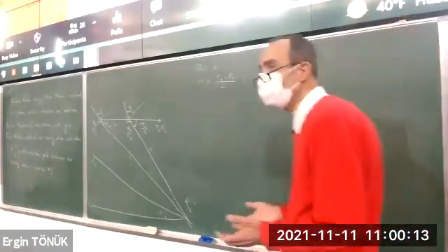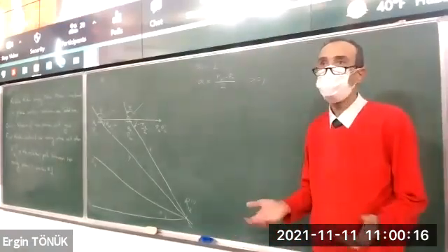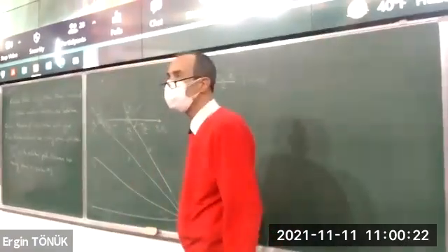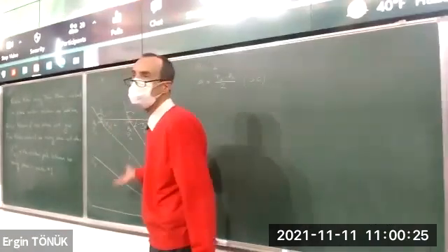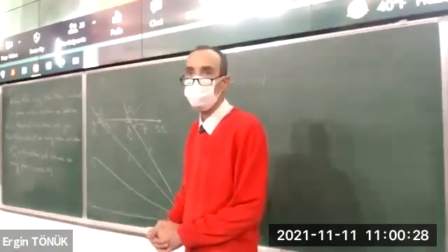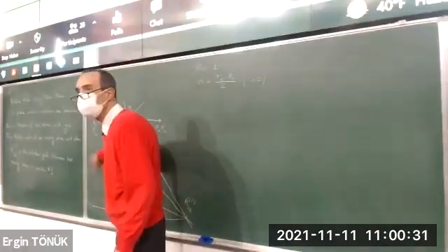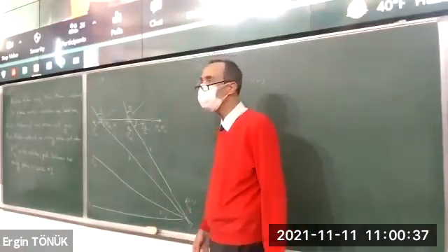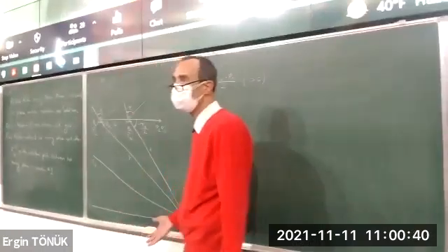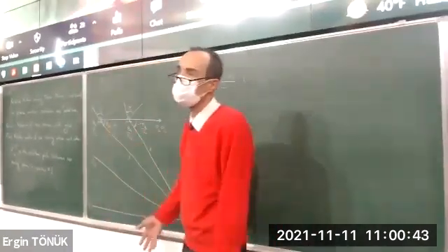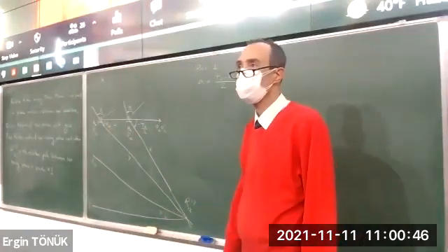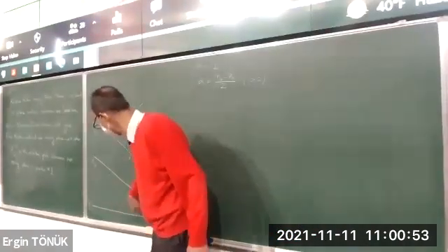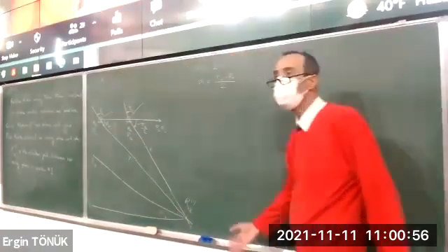That's something very good. Why? Design is an iterative process. You may just draw these lines, select A1, B1, check the mechanism. The two positions might be in two different branches. It's not working. You just move B1 or A1. Okay, it started moving from 1 to 2, but the transmission angle is horrible. Or the link lengths are bad. One of the cranks is 100, I don't know, or maybe 50. So by changing this angle and by moving A1 and B1 on those lines, you can change the design iteratively.